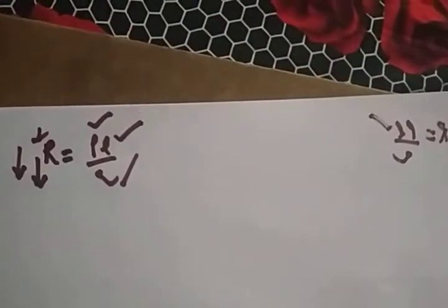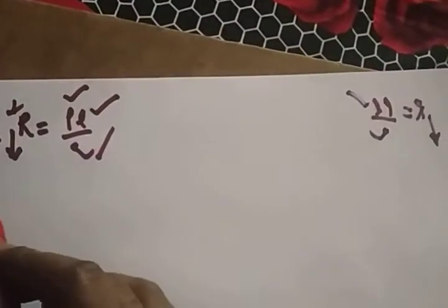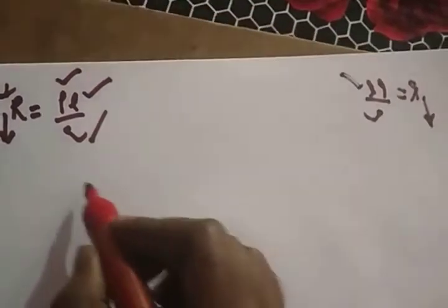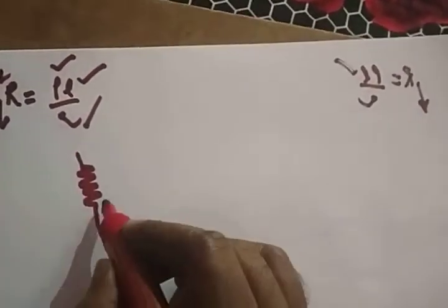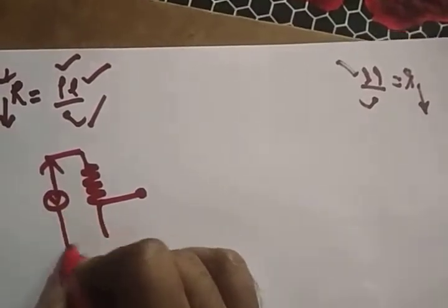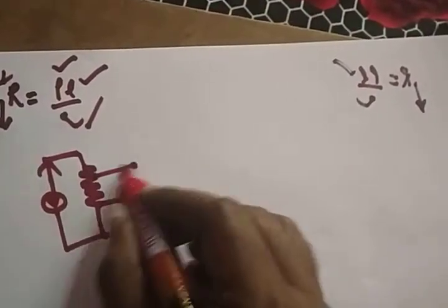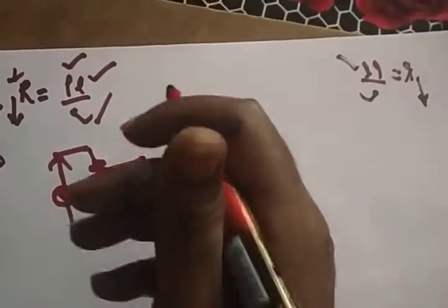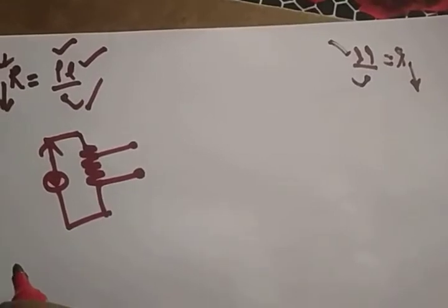And what are the different examples that we discussed? That is nothing but the displacement transducer. Suppose I have a resistance here with a sliding contact, the voltage that you are giving, and a voltmeter. As you change the sliding, the displacement is what you need to measure. Without a transducer it is very difficult, as we don't have any instrument to find out how much displacement you are making in this circuit.